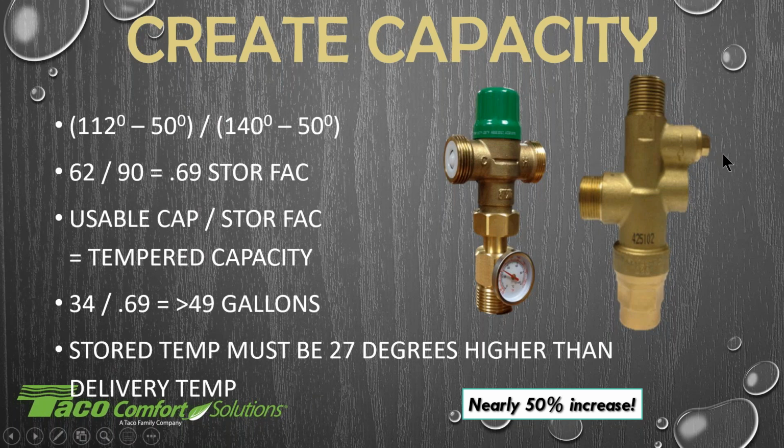On the right-hand side of the water heater mount, the top port here is an adjustment of that water temperature if you wanted to change it. And the bottom port here is actually how we add hot water recirc. So if you had a recirculation system, as we talked about the last couple of weeks, that would tie in right to this bottom port. We also offer the mixing valves with a thermometer, so if you are changing the temperature, you can see what's being delivered out to the house itself.